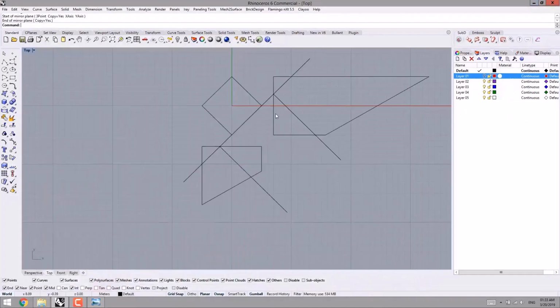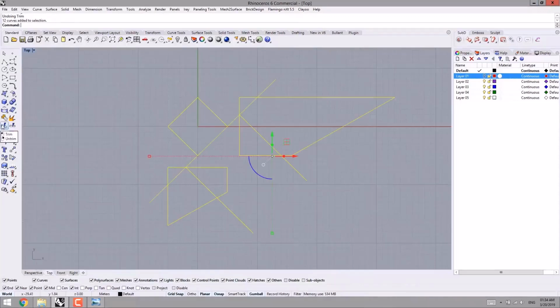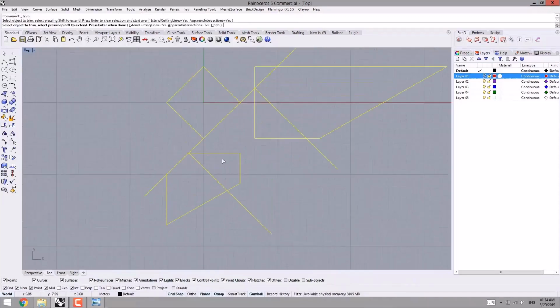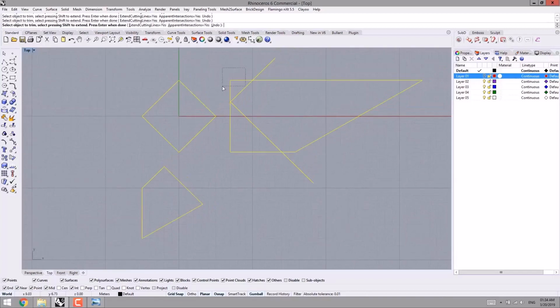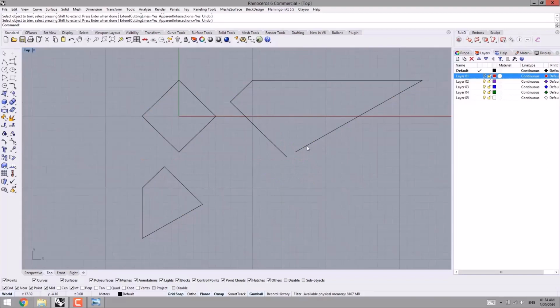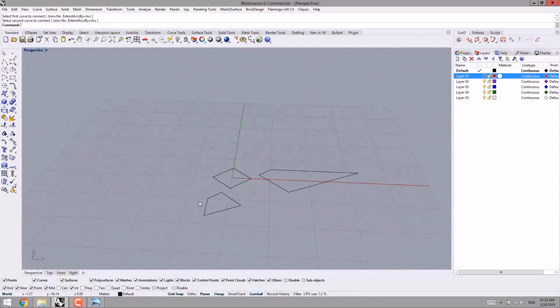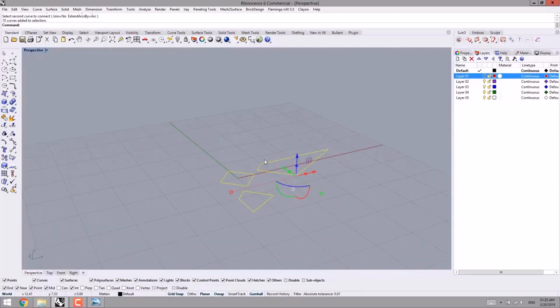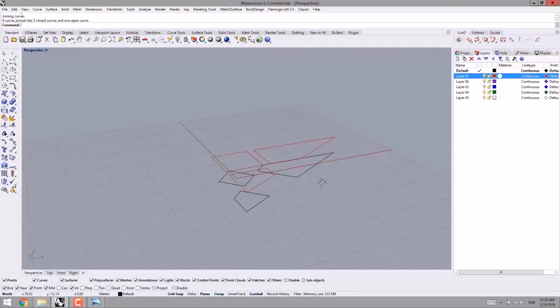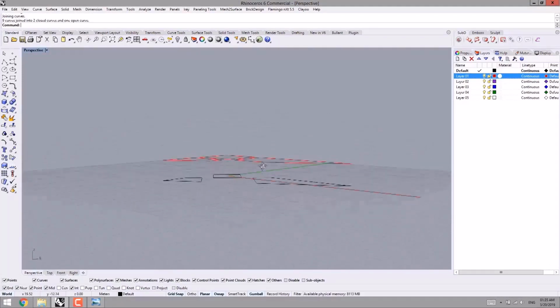And in the continuation, this side is trimmed. Let me get back to Rhino. I select the line, start the command of trim. Then I wanna trim the extra parts, the extra lines, as you can see by this way. And we can connect these two parts with each other by using the join command. I select these curves, Control J to join them. I show layer 1.